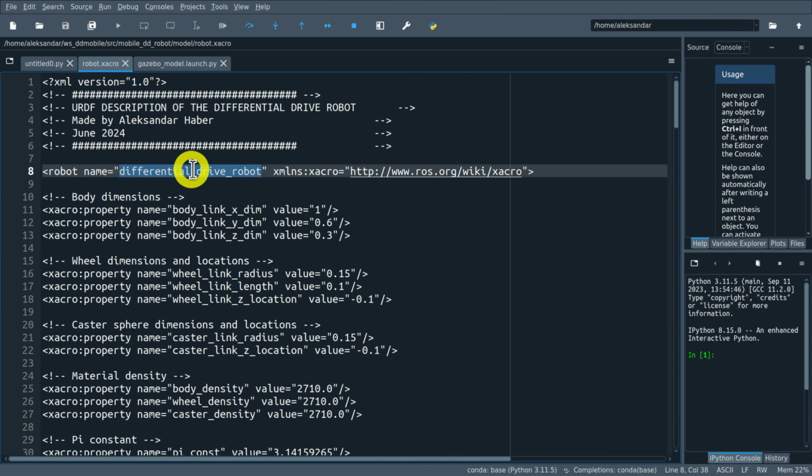and this should be precisely the name of the package we defined in the terminal. Now, this is a relative path to the Xacro file defining the model. Here it is. It's in the model folder inside of the package folder, and the robot.xacro. And this is the relative path with respect to our folder defining the package. This is a relative path to the Gazebo world file, empty_world.world. We are not using it currently. This is the absolute path to the model.